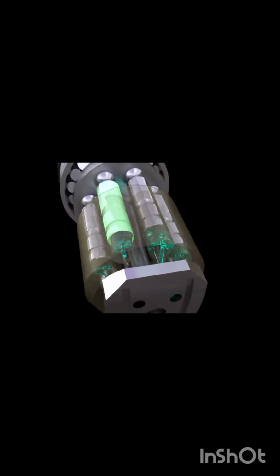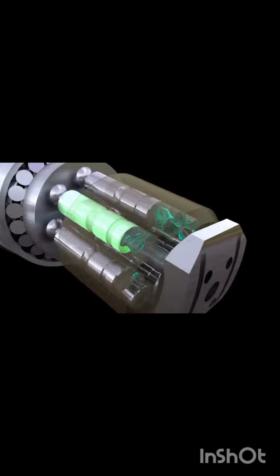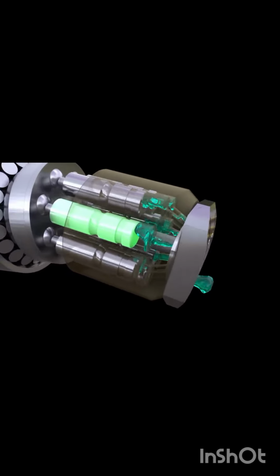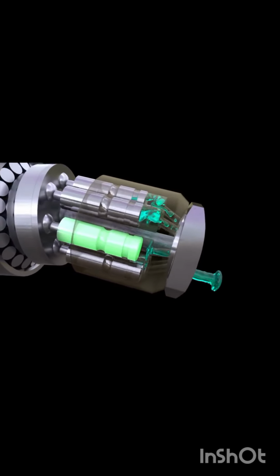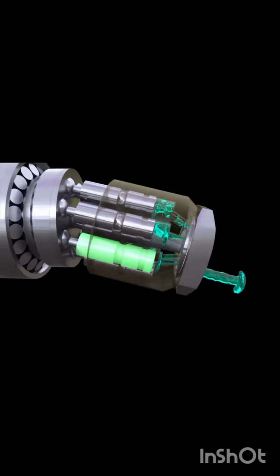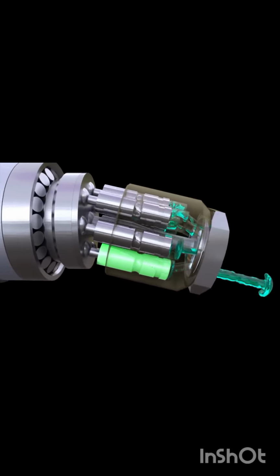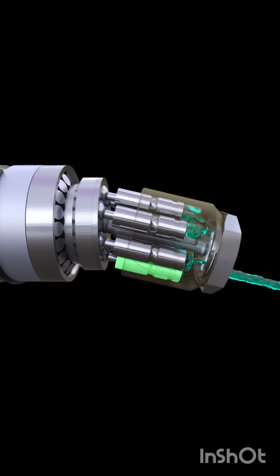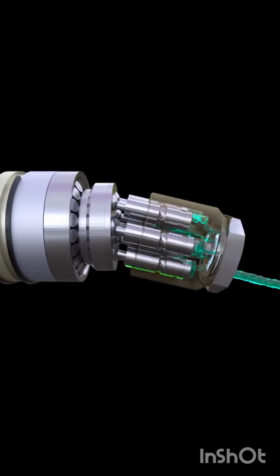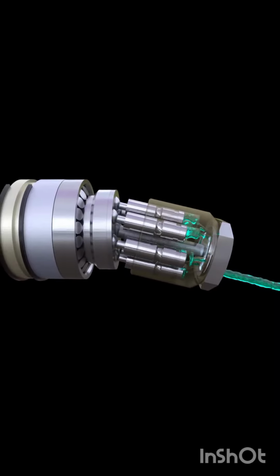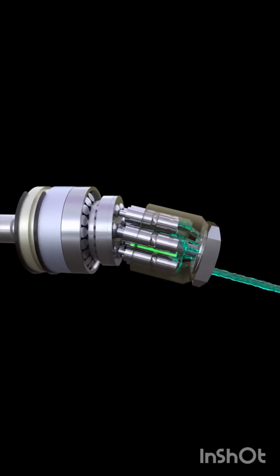chamber under atmospheric pressure. Having reached the extreme position, the piston begins to move in the opposite direction, thus reducing the volume of the working chamber, and the fluid is displaced into the pressure channel. Having reached the second extreme position, the piston begins to increase the volume of the chamber again. The suction begins, and the cycle repeats.